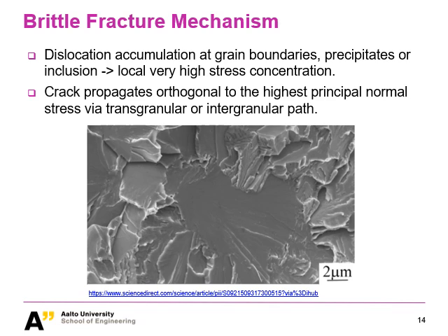Here, I would like to give you a summary of what we have discussed on the brittle fracture mechanisms. As we discussed, we have three main components. Load is always there. The first point is the crack initiation mechanism of brittle fracture. We know the crack initiation mechanism is due to dislocation accumulation at either grain boundaries, precipitates, or inclusions.